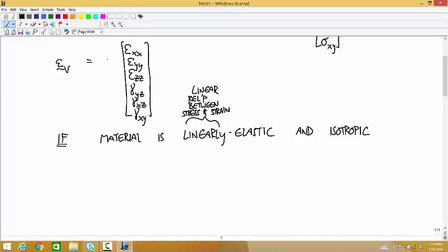Most simple finite elements, like the introduction to finite elements that I taught at Twin Cities Engineering, that's also linearly elastic. So things get pretty complicated when the relationship gets nonlinear. Fortunately, most engineering materials in the range of loads that you use in engineering applications, there's a linear relationship. So the short answer is most of the time when you're doing finite elements, you're still doing linear elastic. You're just doing more complicated geometry.